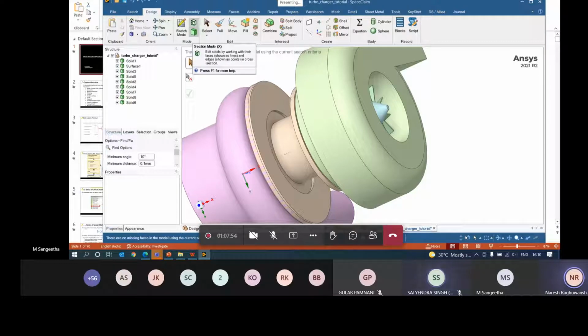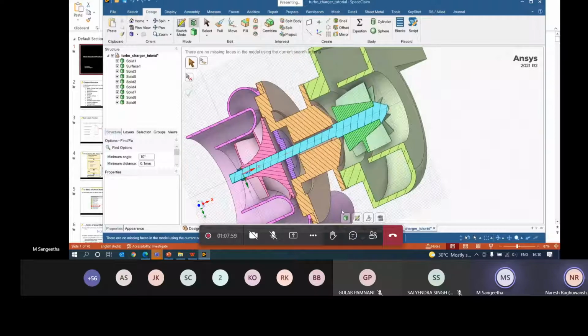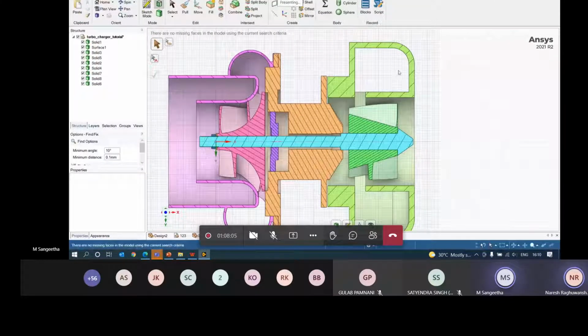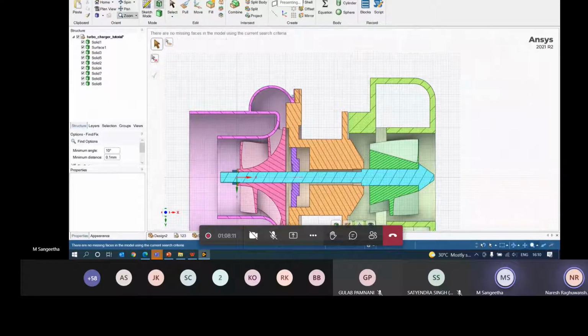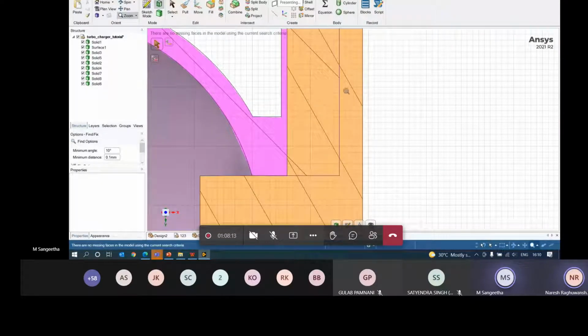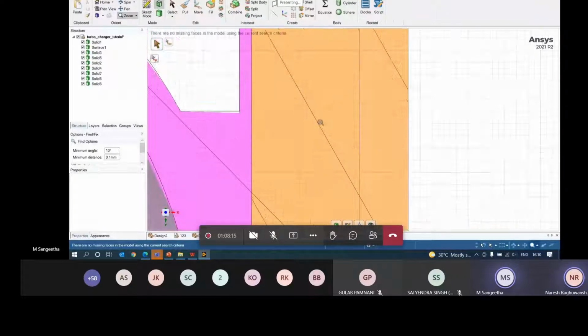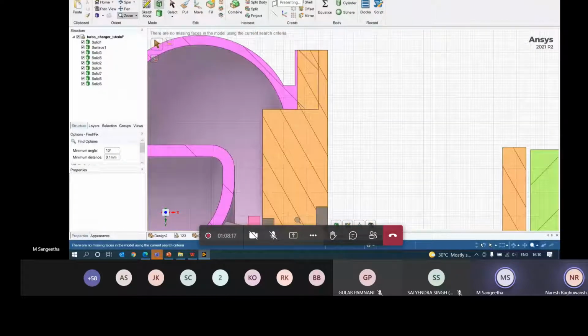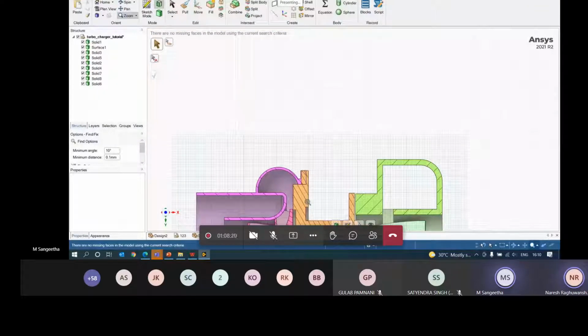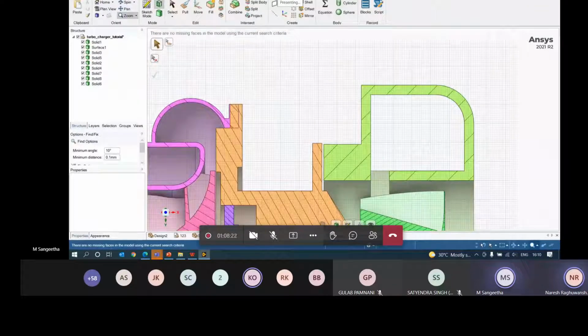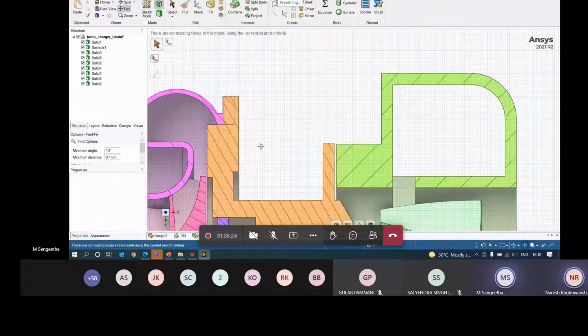Okay, so go to section view, and when you go there, you can create the section view from here and click on plan view. Now here, if you look at it, you can see there is some disturbance in the flow of hatching, right? So here itself, you will understand, yes, there is a problem. But when you look at the other portions, it's clear, right? So even in this way, you can resolve the issue.